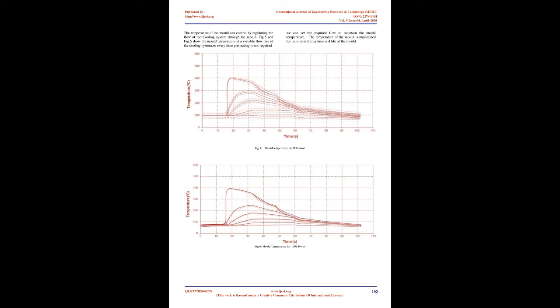The temperature of a filling chamber. When the chamber is preheated before the casting process, the temperature of the cast alloy does not decrease before filling of the mold cavity. The increased rate of cooling of castings in a metal mold in comparison with a sand mold causes an increase in temperature gradients in the casting.